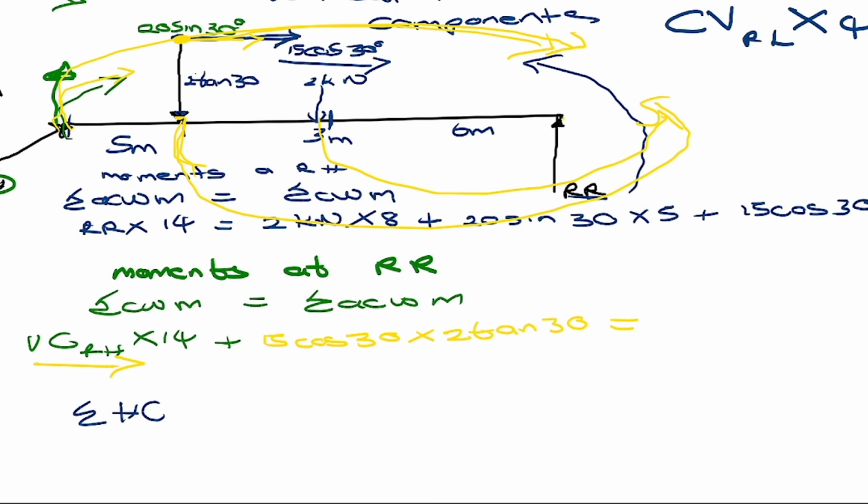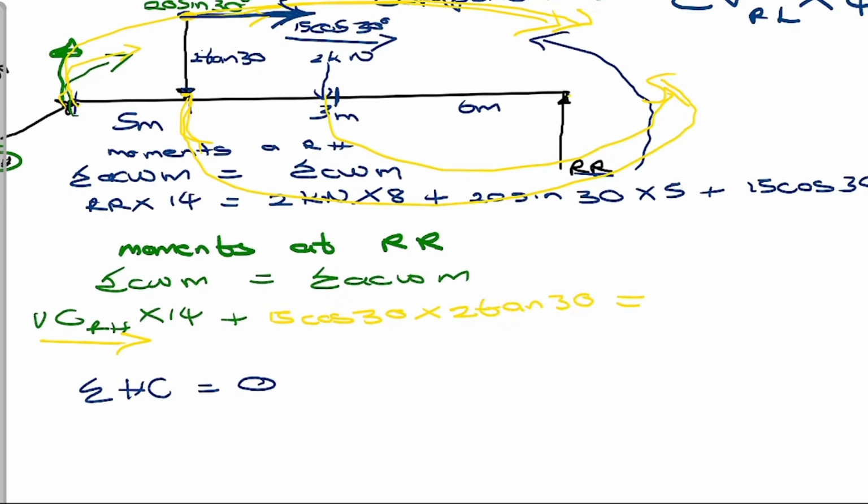Sum of the horizontal components, you have to equate it to 0, and make the forces cancel each other. And by that, I mean that if you have forces that are going this side, add all the forces that are going to the right, and equate them to all the forces that are going to the left, right? So you will take the ones that are going to the right, and then you subtract all the forces that are going to the left. But now you will have the horizontal component of what? Of your hinge as well. Guys, this is some interesting stuff, right?